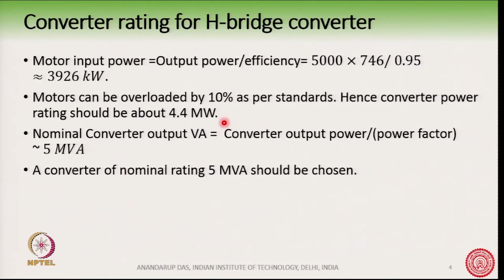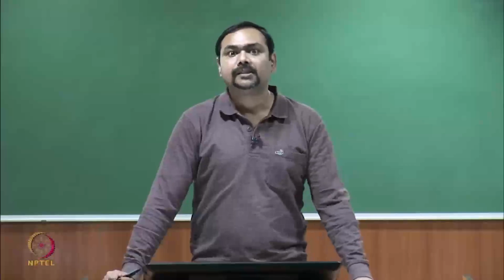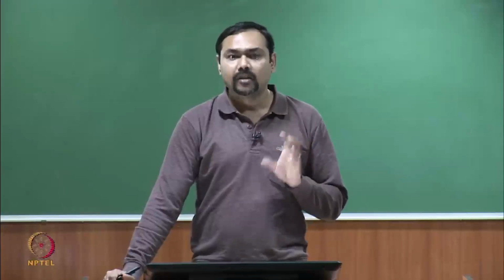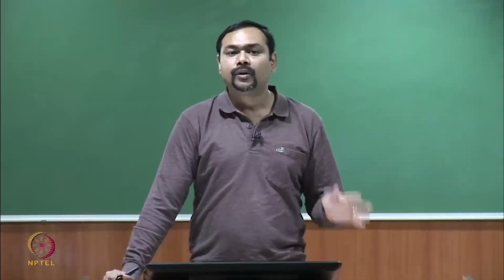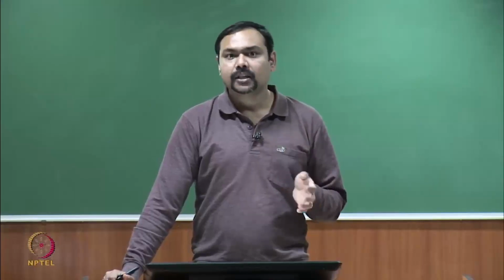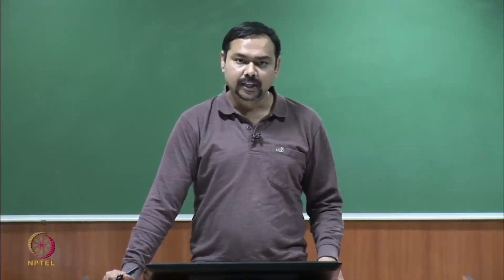So, when you say overload, another question may come up: for how much duration of overload? Is this 10% overload for 1 minute, or is this 10% overload for continuous operation? Generally it is not continuous, it is a short term overload rating.